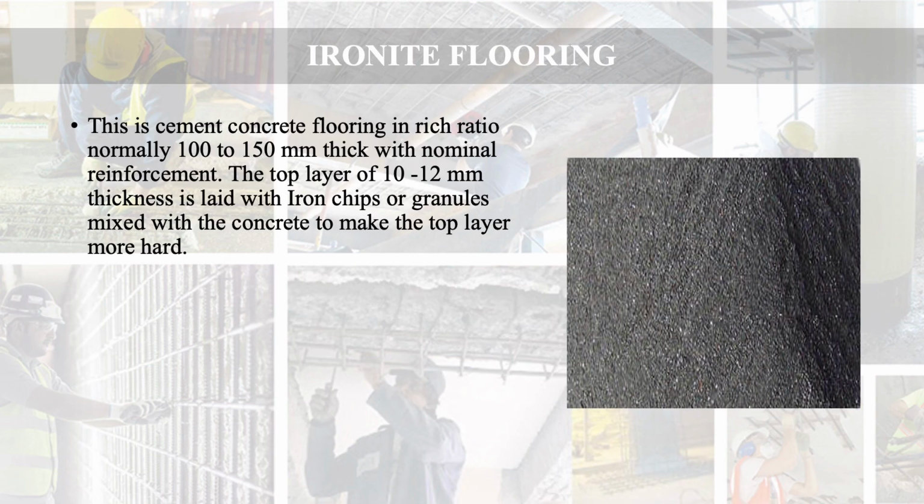This is cement concrete flooring in rich ratio, normally 100 to 150 mm thick with nominal reinforcement. The top layer of 10 to 12 mm thickness is laid with iron chips or granules mixed with the concrete to make the top layer more hard.